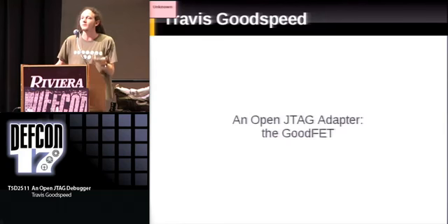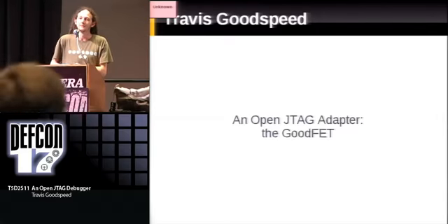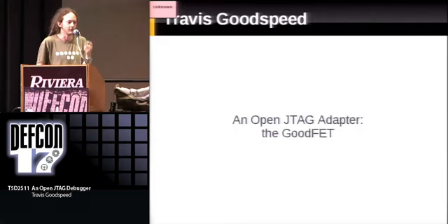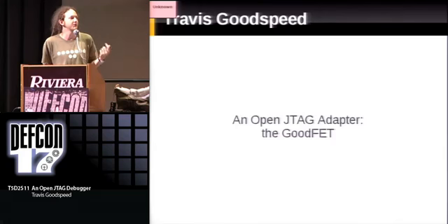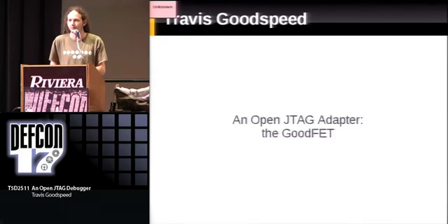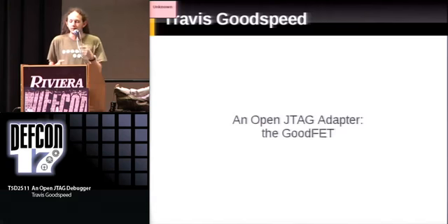Because the MSP430 JTAG programmer requires a driver for a USB to serial chip that's inside of it. Linux had this driver, OS X did not. Even if OS X did, there's no Macintosh application for debugging the MSP430 chips. And the Linux one required a closed source library. So even though you could debug a chip under GCC and Linux, there was nothing that you could do to debug that same chip from a Macintosh workstation.